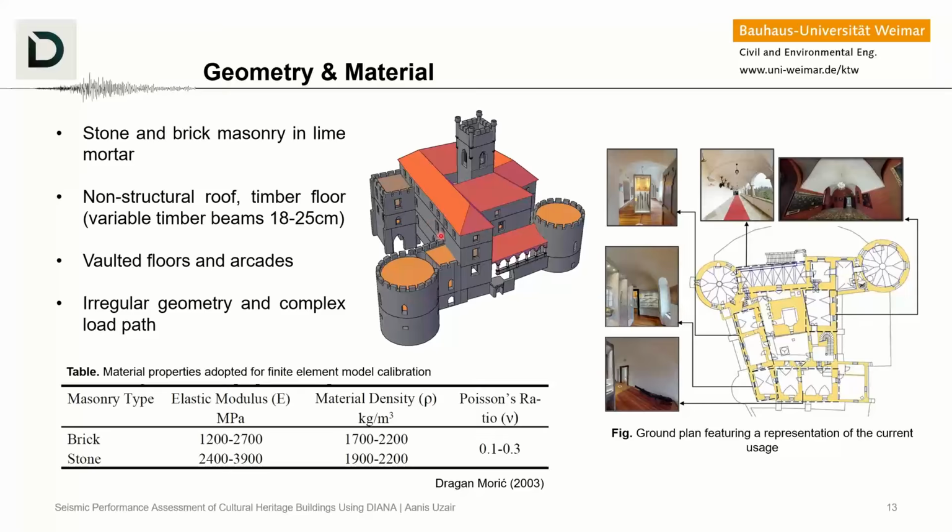And we assign a different material property to different structural systems, but this gives rise to another problem. Now, when we are calibrating the numerical model, we must change each of these sets of materials in a particular range to determine a set of materials that represents the overall structural response, because in the frequencies that we observe from ambient vibration testing, we cannot differentiate between different material properties. So the choice, or the sacrifice, that the user has to make now is calibrating more than one material property, where only one material was assigned to the whole building in the previous case.